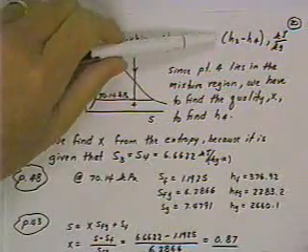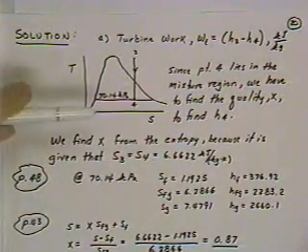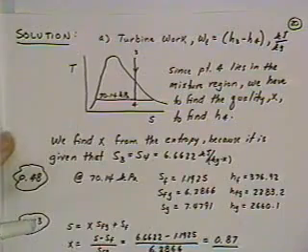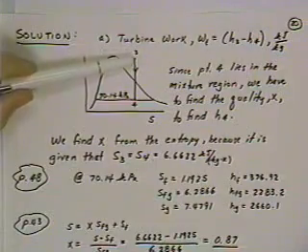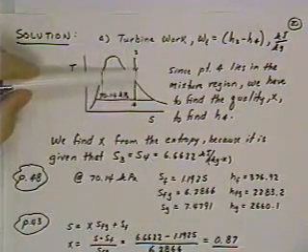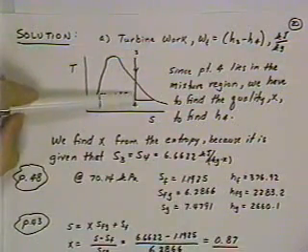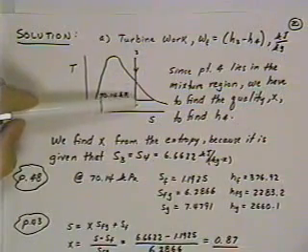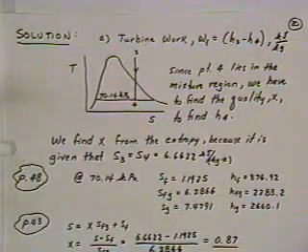And so in the simple analysis of the turbine, the work then turns out to be just equal to H3 minus H4. Okay, point 4 lies in the mixture region, so we've got to find the quality X in order to find the enthalpy at 4. Now, in this particular case though, if it is an isentropic expansion, that is constant entropy, we know the entropy at 3, and so it's got to be the same as the entropy at 4. And so it works out very similar to one of the example problems that we used earlier. You find the quality X, and then after you find the quality X, you can find the enthalpy H.